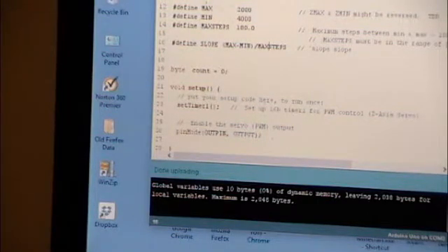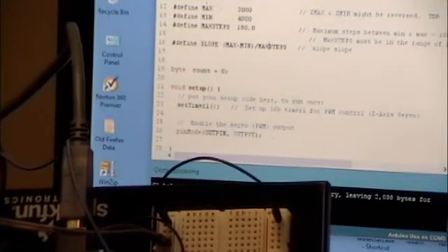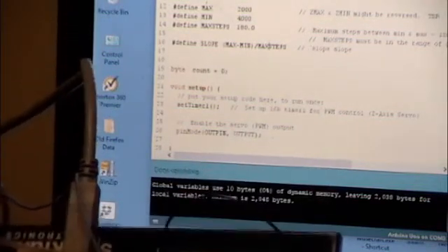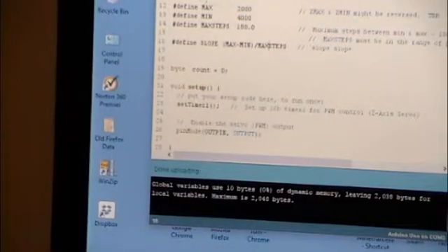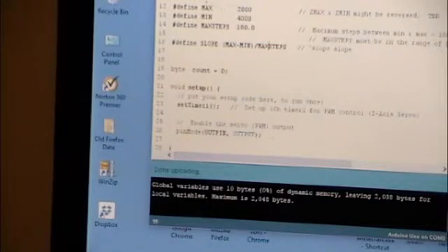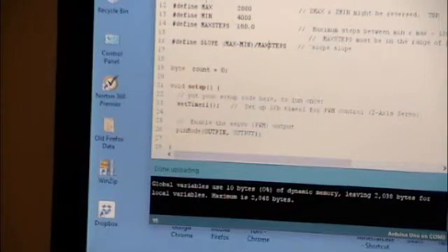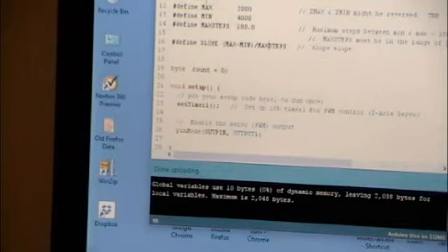He's not doing too bad. That chip right there is the voltage regulator. Since I'm running directly off the USB, it's not going to get hot. But that steps your 9 to 12, whatever volts you got here, down to the 5 volts for the board. And that's a linear, so any current that you're using gets multiplied by the change in voltage, and that's power lost there.